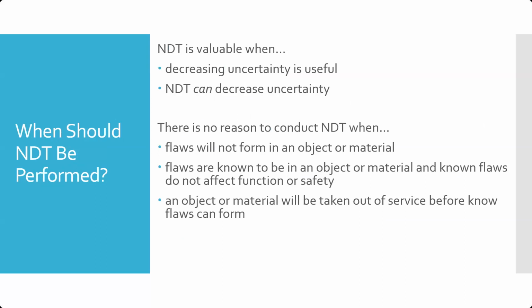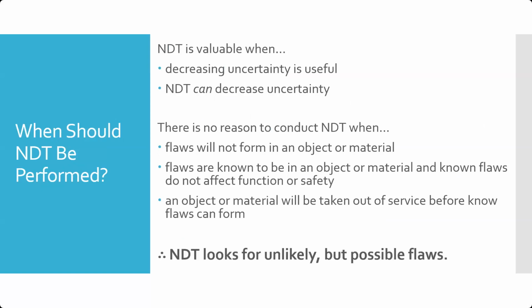And this has kind of led to today, where we have things like aging aircraft inspections. So there are inspections that have to be performed on aircraft of a certain age that don't need to be done on younger or newer aircraft, just because they wouldn't have had those flaws start to form yet. So therefore, NDT looks for unlikely but possible flaws, and that can make it a very frustrating and difficult thing for a lot of people to perform.